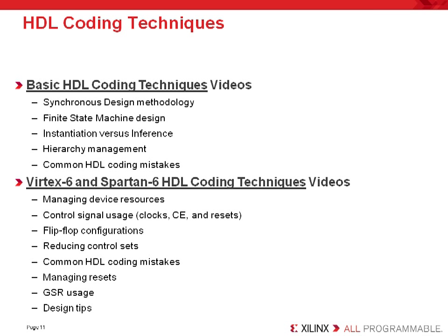When we start getting into the specific architecture coding techniques, now we're talking about managing device resources, specifically muxes, shift register LUTs, and some of the dedicated functionality that's built into these FPGAs that requires particular HDL coding techniques, including flip-flop configurations, control signal usage, reducing control sets, etc. All of this is very important to optimizing the speed of your design.